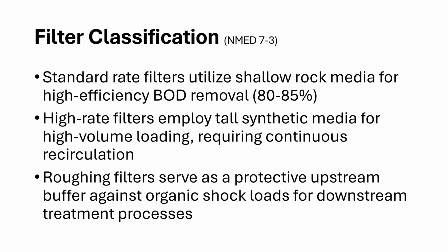The idea is those roughing filters are going to do what they can to take a good chunk of the BOD out of the wastewater at this point, so that we don't shock anything downstream and overload it with a bunch of organics. That's a roughing filter.